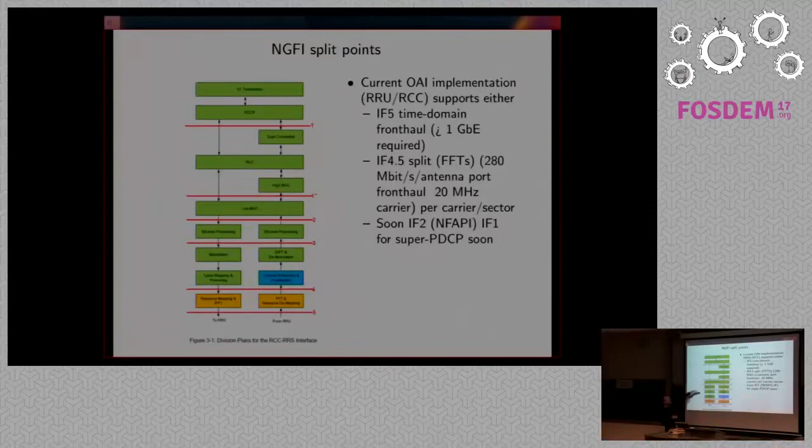This is a protocol stack, say, of a 4G base station. You have the radio interface, so this is your IQ streams, like you would be handling in UHD. This is the first stage of the input, the transfer of the frequency domain, and they give that a number. They call it interface 4. Then you can go up further in the stack. They define this one, interface 3, which is just before the bit level processing. Then another one, interface 2, and then there's that one up there, interface 1 prime.